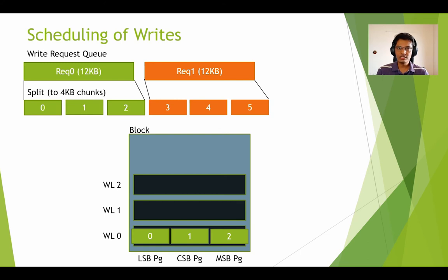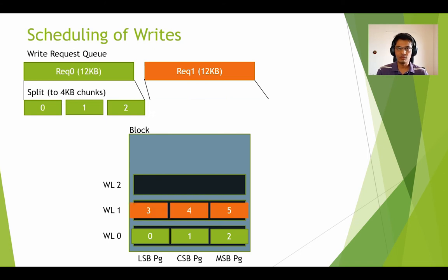If we program all pages in a melded page in one shot, it becomes susceptible to cell-to-cell interference. It is a scenario where programming all bits in the flash cell present in this word line results in a significant threshold shift in the adjacent cells, thereby corrupting it. So in this example, writing word line 1 will corrupt the contents of word line 0.